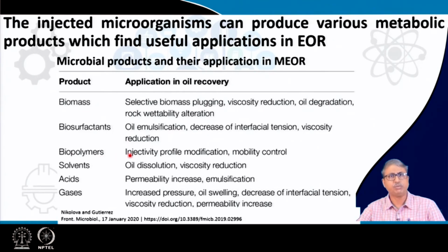Biopolymers are responsible for facilitating the injectivity profile modification and mobility control. Different solvents will allow the dissolution of the oil or viscosity reduction, and different acids which are produced by the microbes will help in enhancing permeability or the emulsification process. Different gases which are produced by the microbes increase the pressure build-up, which is very important, so that the entire thing will be pushed towards the oil well, and you already have a high pumping system working there. Oil swelling, decrease of interfacial tension, viscosity reduction and permeability enhancement.